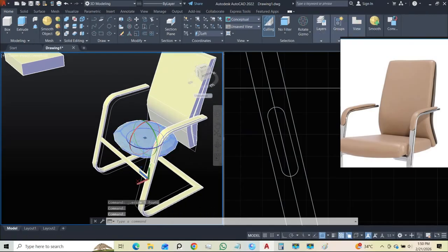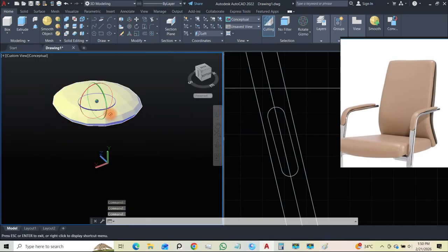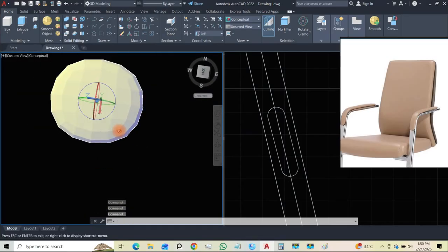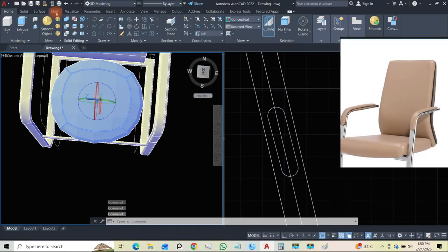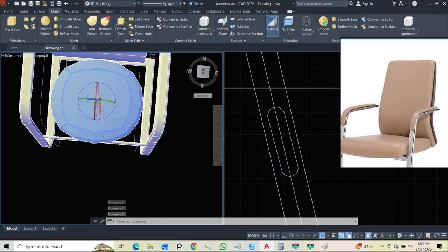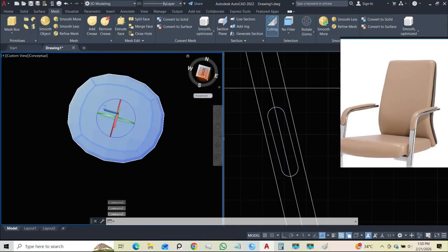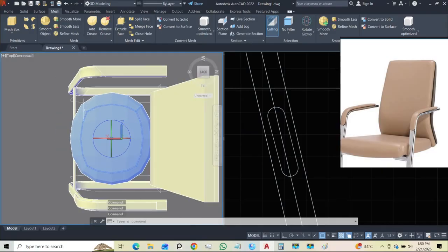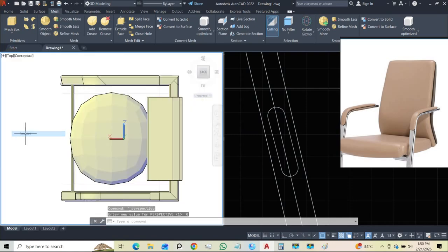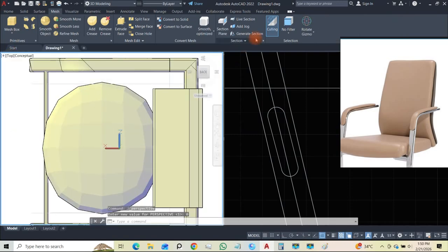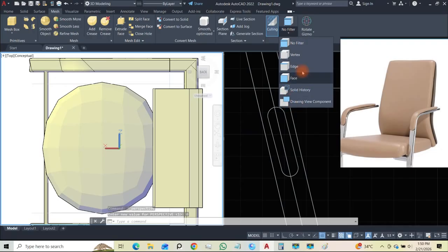So if I select this, for me to now start controlling this mesh, what we can do is under my mesh there is a selection filter. Right now I'm selecting this object as a whole, and I want to be able to select it as maybe the point or the mesh or whatnot. So I can come to the filter, I can select by face.